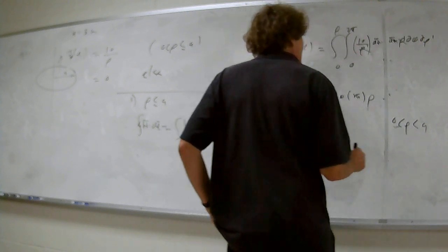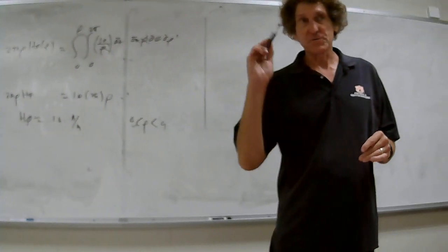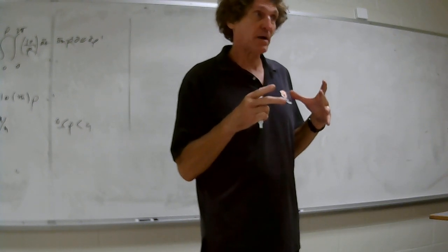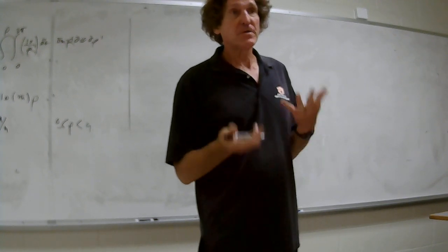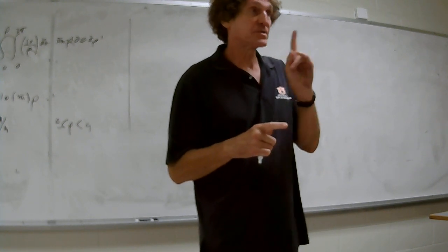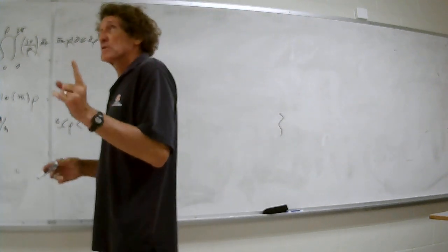Does everybody understand that part, by the way? It's a straightforward integral of H dot dl around a closed loop, which is just the circumference, 2 pi rho, times H phi. Everything going inside that loop, penetrating it, is in the az direction. It's just the integral of the current density over the surface.